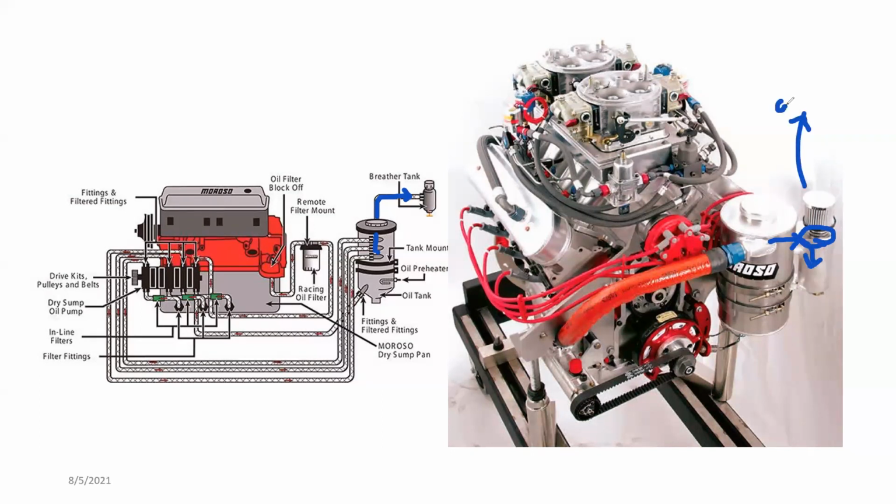It only has air outlets, and no vaporized oil comes out of it. That's why it's using this tank. Otherwise it's possible to just keep this breather line open here, but that could end up venting lubricant oil, which is not the ideal solution.